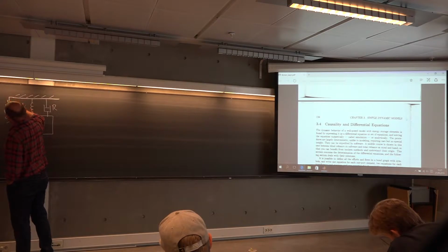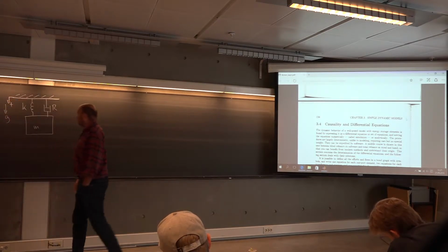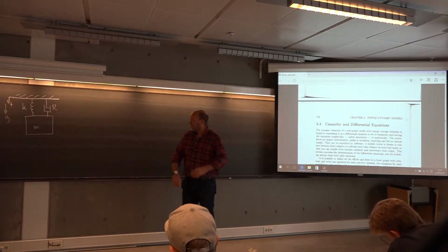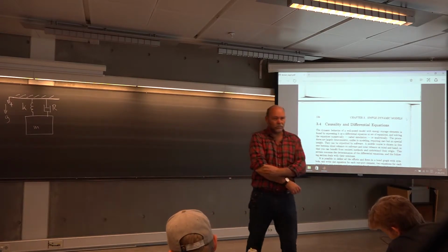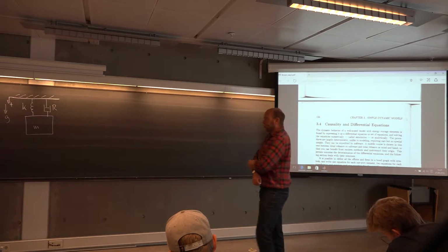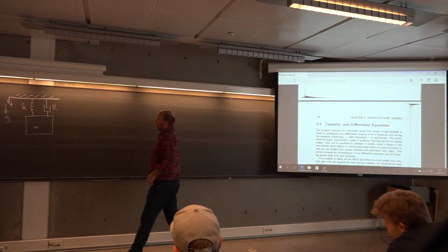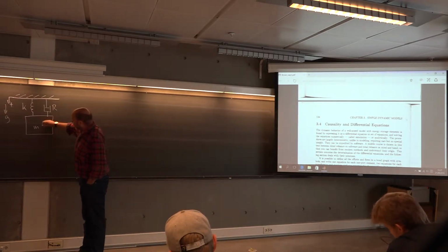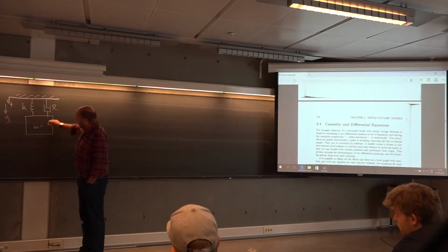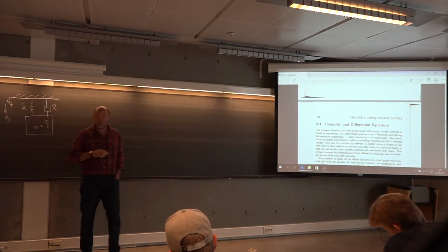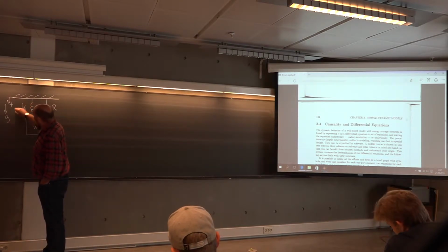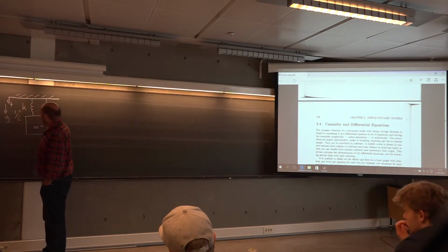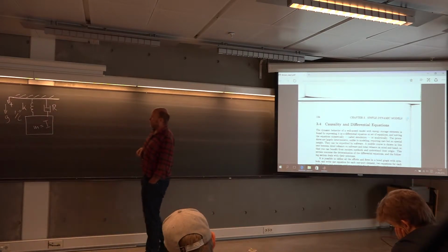Well, why not take it downwards? Find the equation of motion, the state equation for that problem. First of all, we translate M, that is an inertance, spring stiffness K, that is 1 divided by C, R for resistance, that's okay.